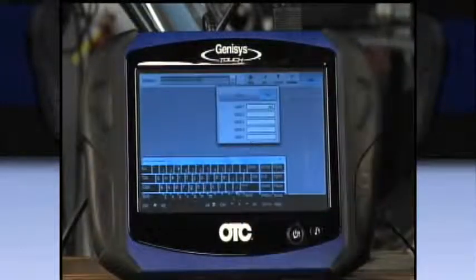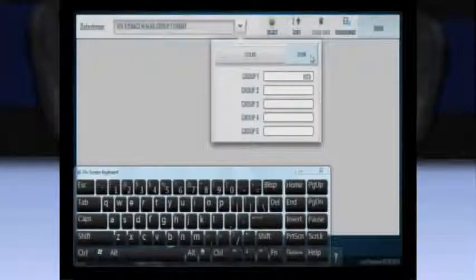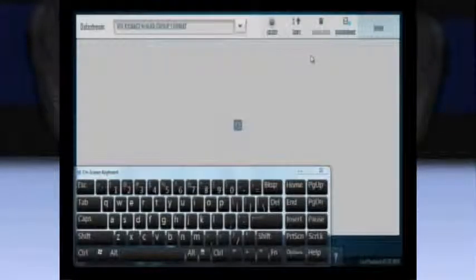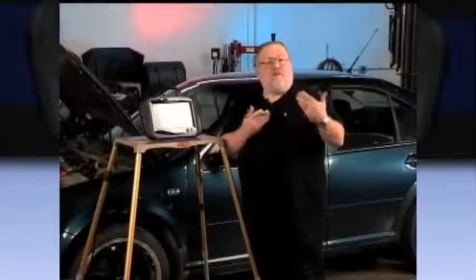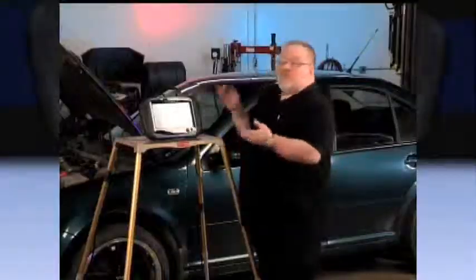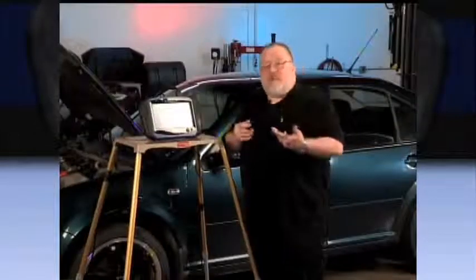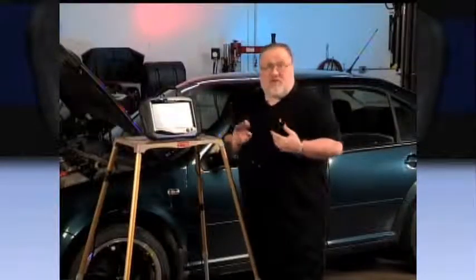And as you can see, now I've entered group 003. Once I've got group 003 entered, I select Done. The scan tool now is going to interface with the vehicle again, and we're going to pull up the live data stream. Now, this is a diesel, so right now I don't have the vehicle running, so we're just looking at the representation of the data screens as opposed to live data, because you wouldn't be able to hear me with a diesel knocking in the background.